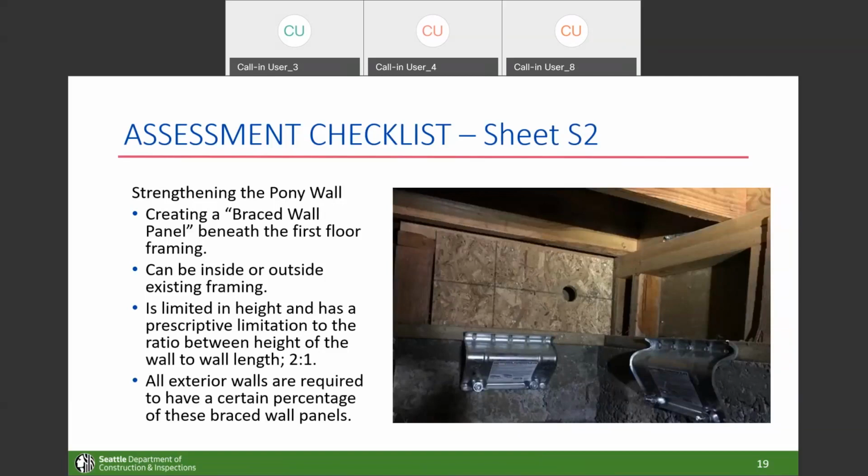Sometimes, even though it was pressure treated, it can be an issue because of the age of the wood, or if the wood itself is deteriorated. 2x4s can work as sill plates, but that would be something on a case-by-case basis. It's a good question. That would be something to ask in the Q&A, or better yet, try to get a picture of it and then talk to somebody here.